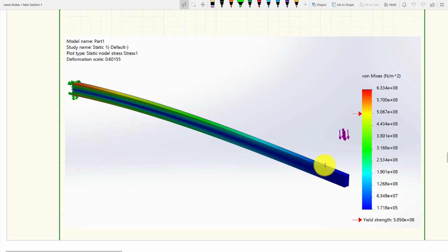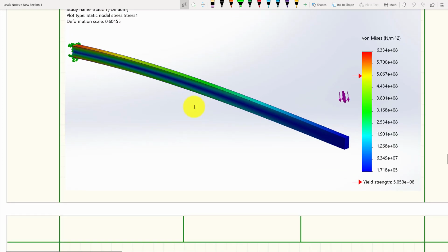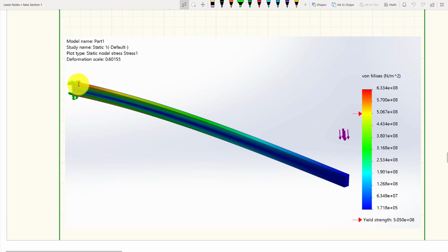Now, if I was looking at the stresses in this beam, remember you're calculating stresses here, what do those stresses look like? Well, if I was looking at the moment diagram, I'm going to see that the biggest moment is probably going to be about this end down here, and I'm going to see the highest stresses down here. Now, let's talk about what's going on over here, because eventually you guys have the potential to take some FEA courses and more advanced courses past strengths of materials that will do this kind of stuff. And what we do is we simulate, we mesh, make like a screen network of nodes across that part, and we do lots of calculations.